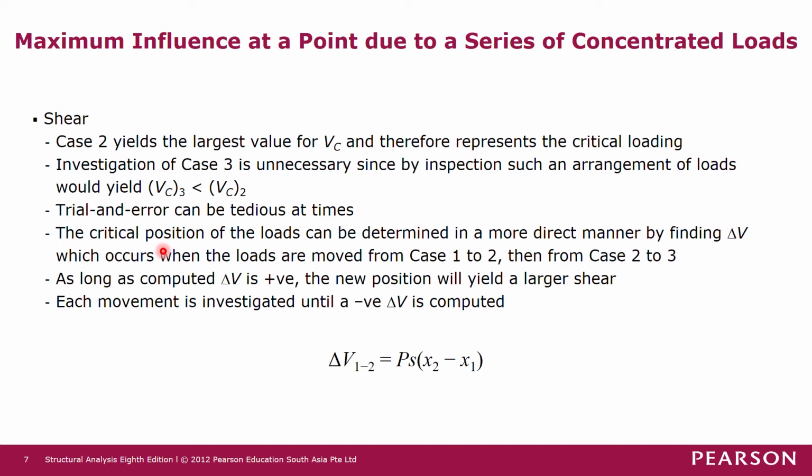So the critical position of the loads can be determined in a more direct manner by finding the change in shear. This is not the shear force, but the change in shear force, which occurs when the loads are moved from case 1 to case 2 and then from case 2 to case 3.